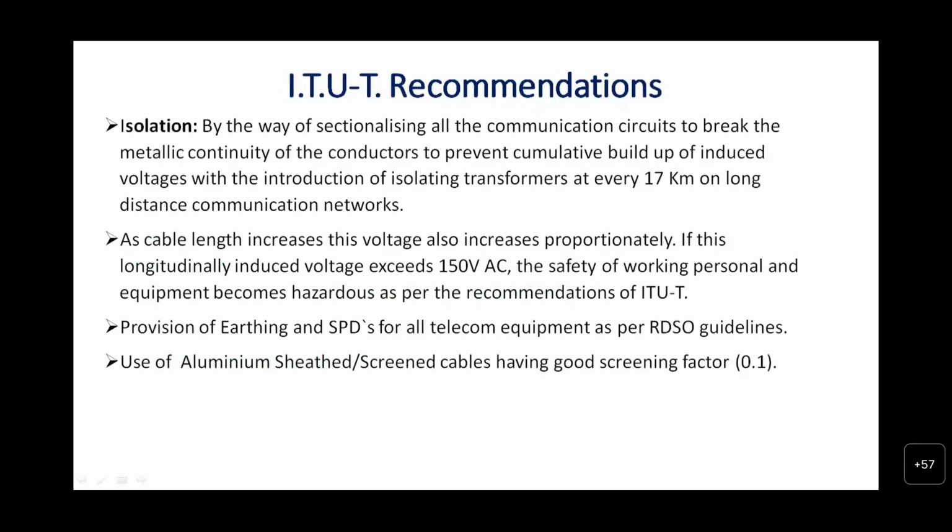As far as our South Central Railway is concerned, this situation does not arise, because the block sections are every 10 to 15 kilometers, so the 17 kilometer length of sectionalization is not arising in our South Central Railway. If at all it does arise, we have to sectionalize by isolation transformer. As cable length increases, this voltage will also increase proportionately.